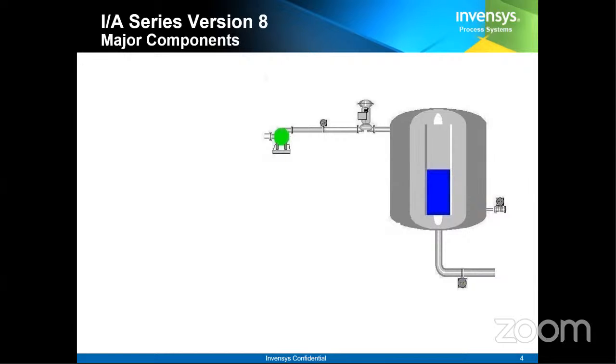Right now, in the previous seminar, you were discussing a boiler with a tripping concept, where Mr. John was talking about a particular pressure sensor, which is a very critical one, for which they cannot rely on a single transmitter. So they have 3 transmitters with a logic of 2 out of 3. Out of 3, if 2 transmitters are saying the pressure is low, the value will be accepted as true, and based on that the whole system will trigger. That is a real application.